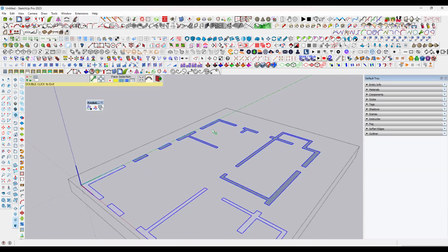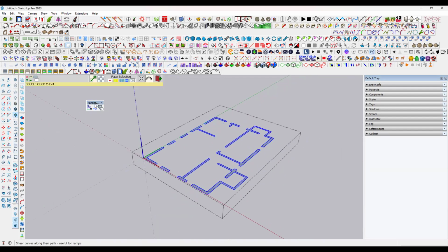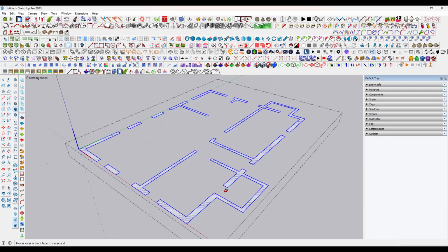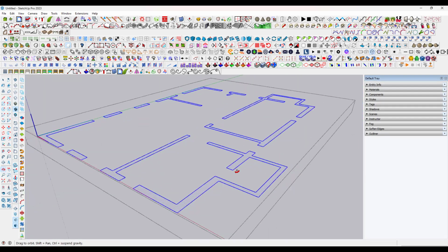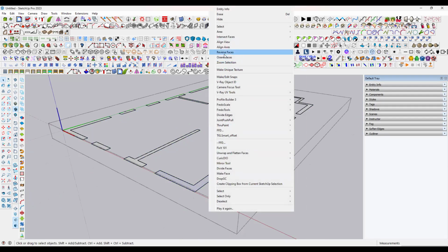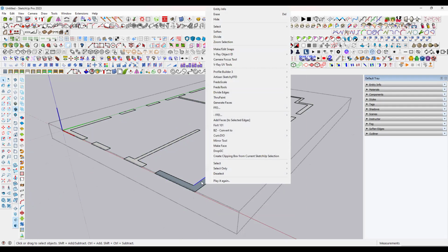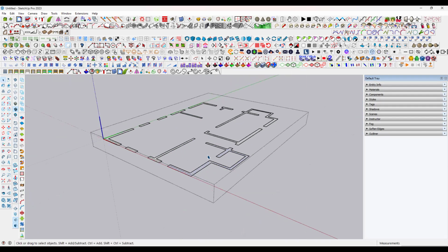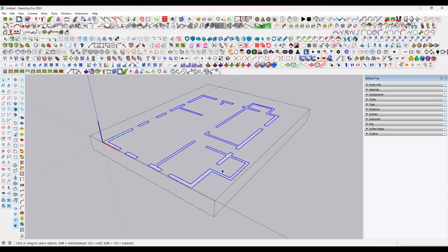But even so I'm doing it individually, alright? Again here we have one more option. The name is Tool for Reversing the Back Faces. This is a separate plugin again. In this situation, I'm holding the mouse left button and if you keep moving over the surfaces like this, every surface is going to be flipped. Generally how we do it, we give a right click and choose the reverse faces option, and instead of that I'm going directly with this button to reverse the faces.